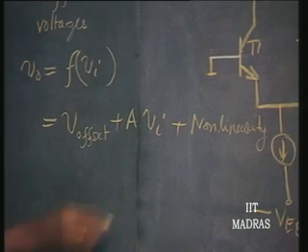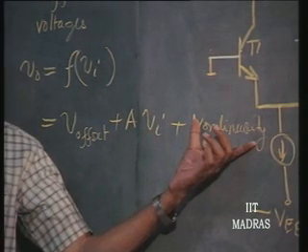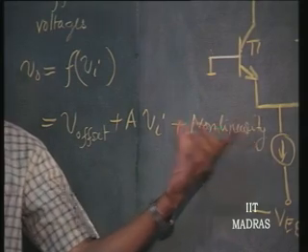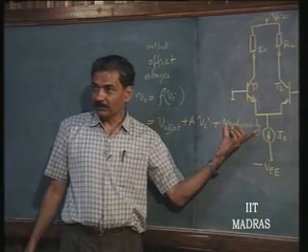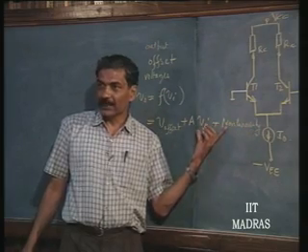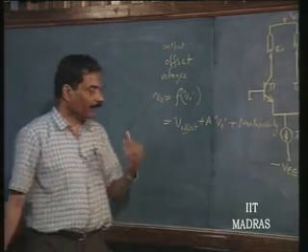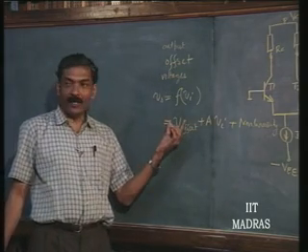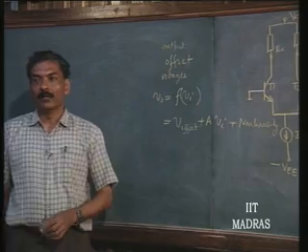So, we are biasing the op amp or the differential amplifier in such a manner that these terms are made very small for a given VI. That is why biasing becomes important. Apart from that, we would like to make this offset also go to 0. Why, you might ask?